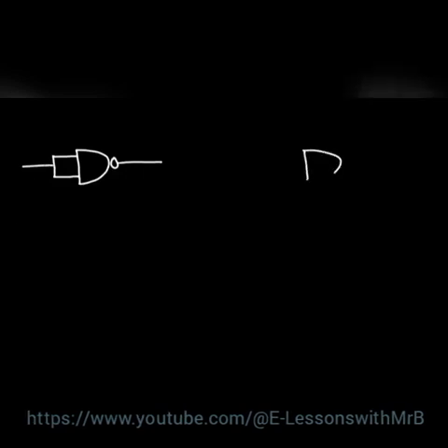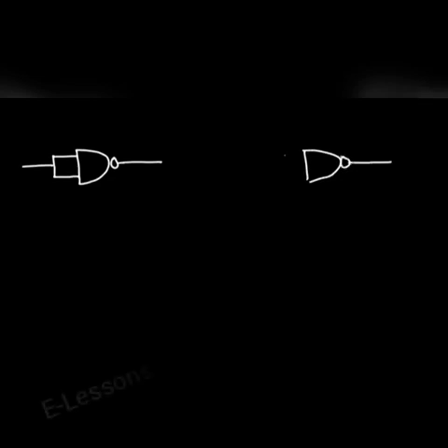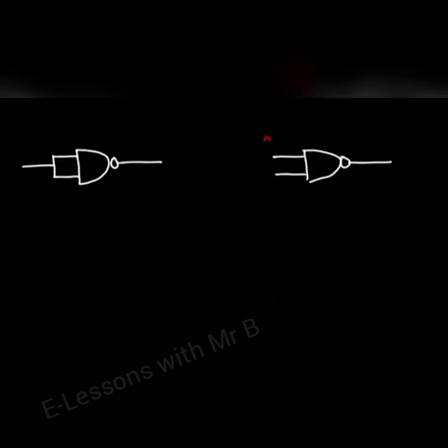Now here's a question for you. Let's say we have a NAND gate, and we take the two inputs of the NAND gate and connect them together. What type of logic gate do we now have? What would you say? So let's compare it to the original NAND gate. So this would be A and B, and we would get A times B, but the complement of that result.